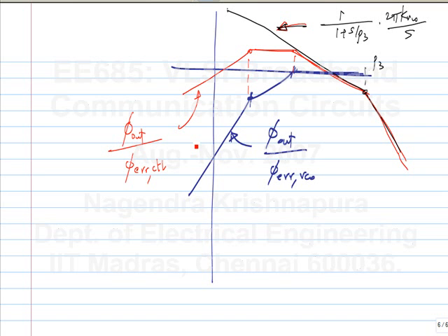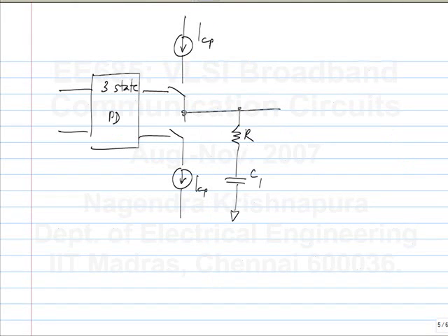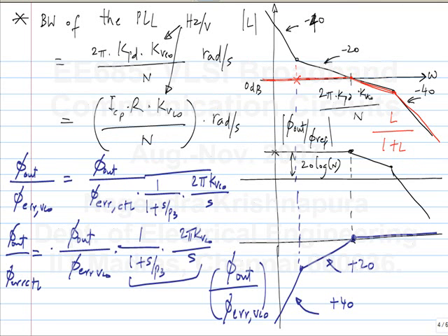Okay. So in this case, you are using a clean input and you are trying to clean up the noise of the VCO. In that case, you use a wide bandwidth. Okay. Wide bandwidth means that this low pass transfer function moves out and this high pass corner also moves out. Okay. So more of the VCO's error will get filtered out.